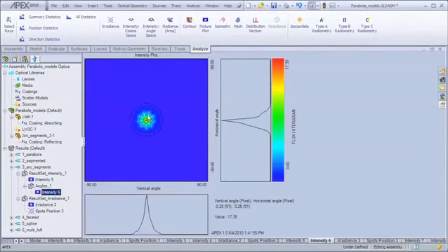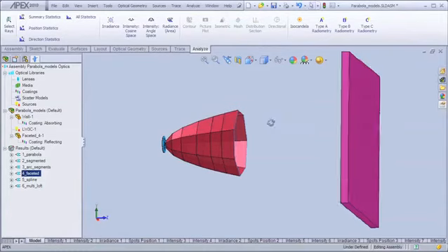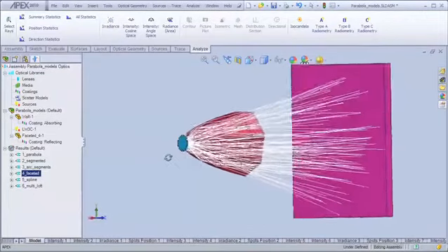And we also see some information relative to how the angles at each facet edge affects the light. And if we were to count these, it would be an easy way to see how many edges I had put on my polygon. In this design, we've broken our parabolic section into linear segments, and then we've also swept those based on the polygonal output face. So what we can see is these flat edges here, and we have flat edges here as well. So let's take a look at the results of the ray trace.